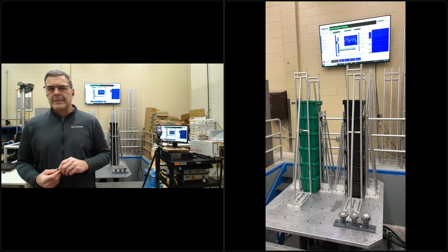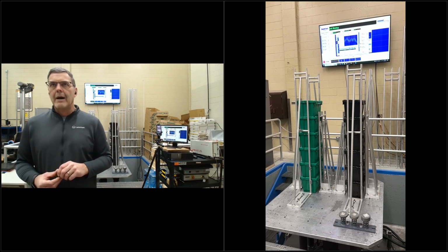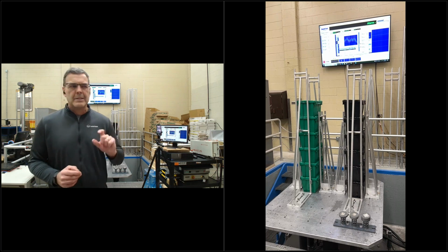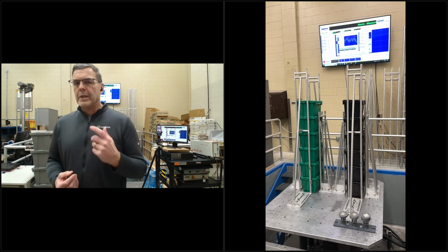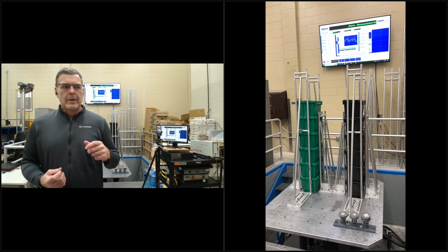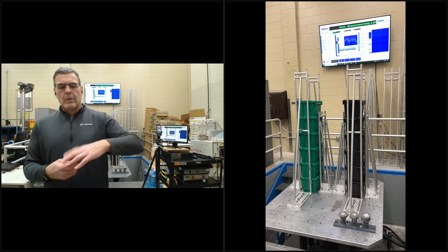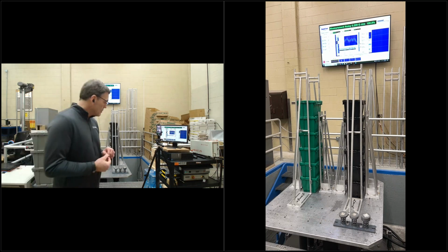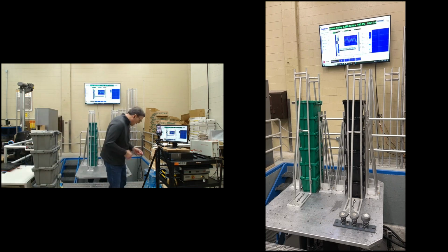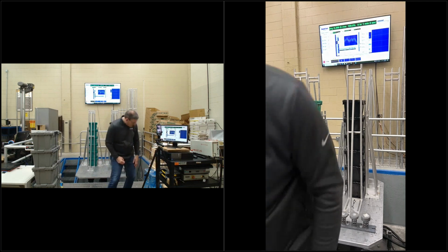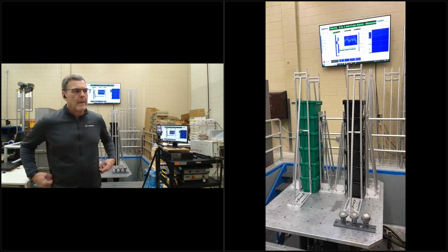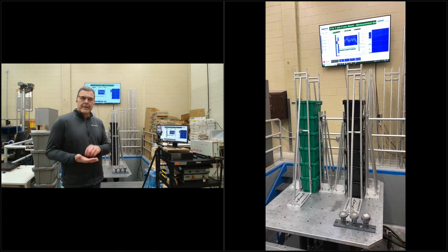For vibration testing, because we often are not shaking it so intensely, especially in product testing using sine vibration, the input isn't crazy high intensity, such that it would throw the accelerometer off of whatever it's attached to. So in that case, we use glue, beeswax. We can use beeswax, and I don't have any out here by the machine right now, but I've used it here at Michigan State in the past. So beeswax is another thing that can be attached for vibration measurements.